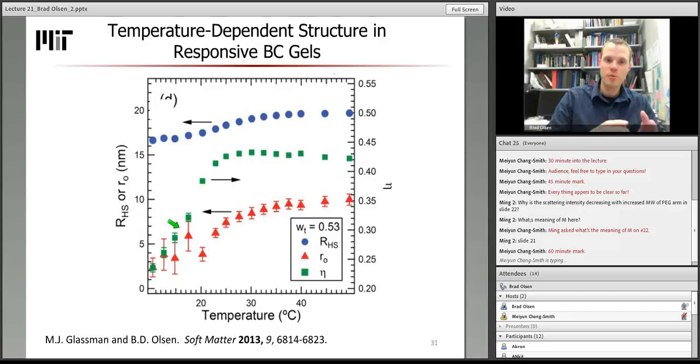And so really neutron scattering gives us a powerful way in situ to measure the temperature evolution of the materials as we heat them through the structural transition. We can then correlate these structural transitions with mechanical response, and what we actually show is that to maximize the increase in modulus and the increase in toughness in these materials, the key is not to maximize the temperature where we have the best developed structure, but really to maximize the packing fraction eta.